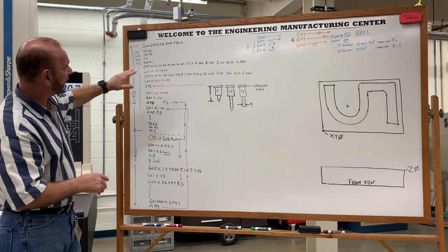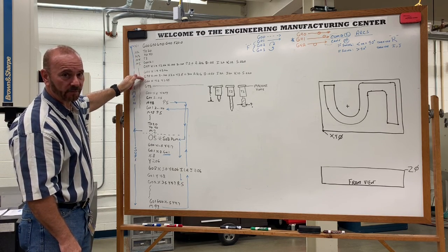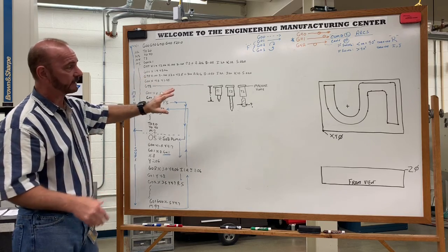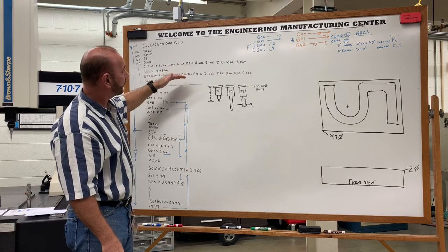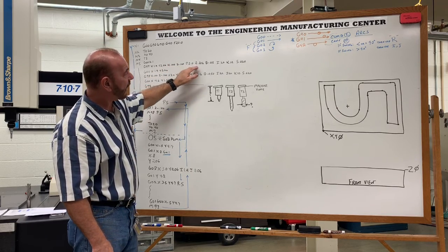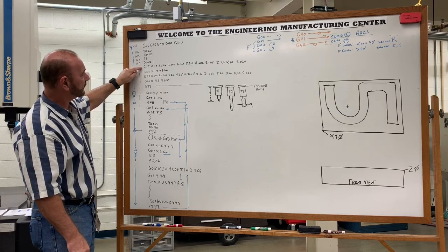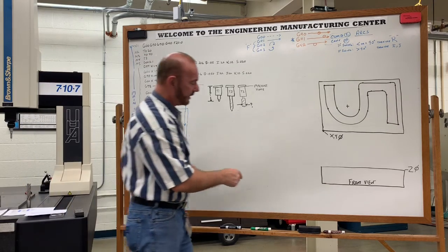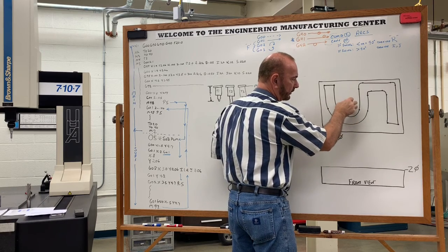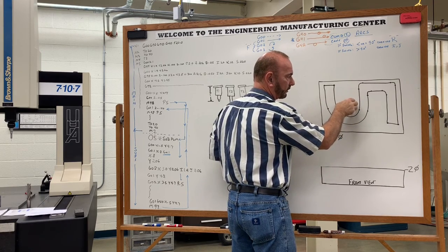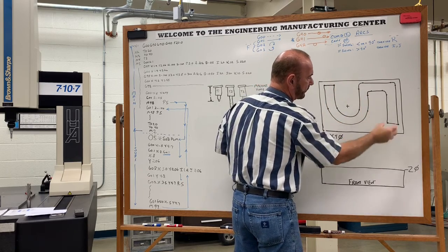In this particular case, you guys did not have to watch videos 1 through 5 in order to complete the assignment, but just as a reference, this block and this block do two different types of operations. Now this G77, which does a circular pocket, had a circle in your original drawing here, and it took the material from the center of that circle out. It had a rectangle drawn in here and a rectangle drawn in here to remove material.